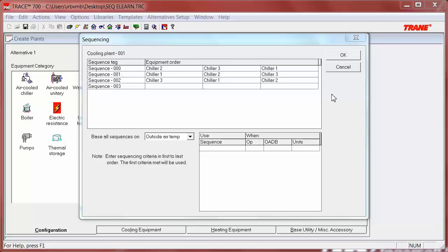Please note, if using the less than or equal to operators, the opposite will be true and you will want to start with the highest value. Since the weather location we've chosen is in a heating dominant climate, we'll start with a significantly low temperature to ensure there are no gaps. If unsure where you should start, you can check your weather data to ensure you are starting with a low enough or high enough temperature.